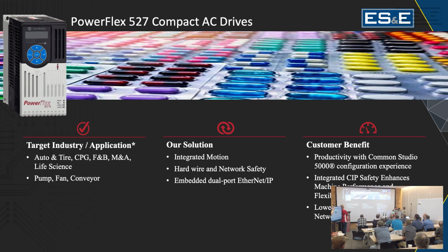Yeah, so as we move on to a couple of the Ethernet devices, we've talked about the PowerFlex 527 a little bit. Hayden kind of jumped the gun earlier, sorry, but we'll bring that back up. There is a reason that we use the 527, and that was for the SIL safety over Ethernet. Like Hayden brought up, all of this information is over one Ethernet cable now, so we're not having to run inputs and outputs and things like that.